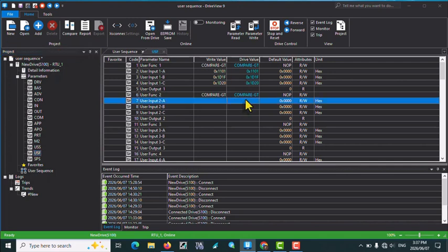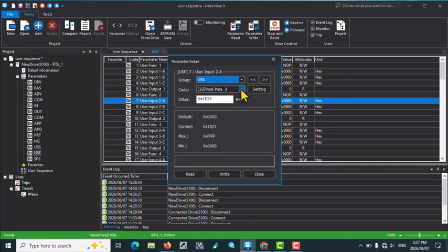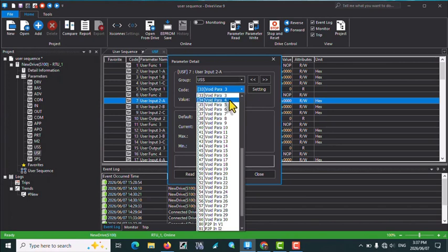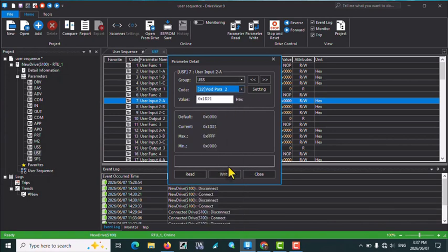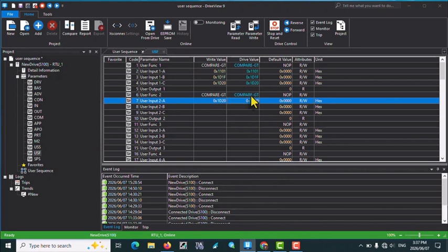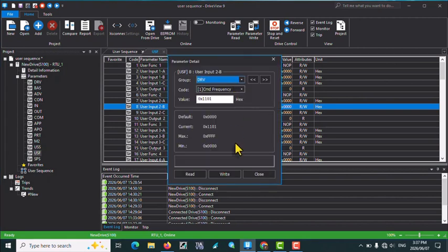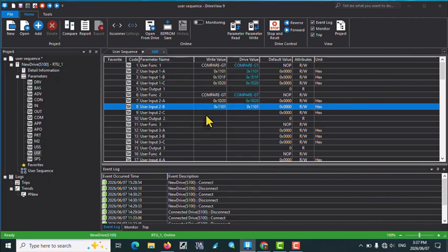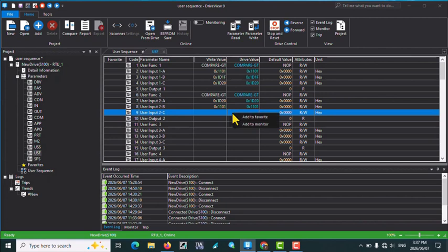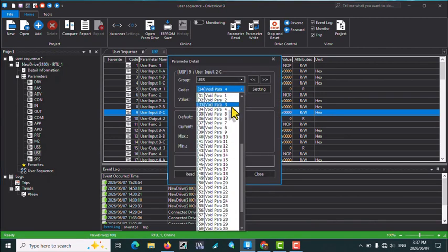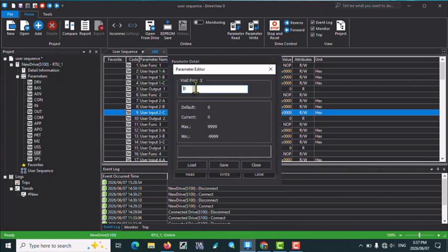First, I'm using the constant value 5, the same constant 5 I used in function 2. So I select function 2, and 5 will be my second input. I assign the drive mode or the frequency set point to it for C as well. I am going to use the third parameter, and then I'll assign it a value of exactly 1.